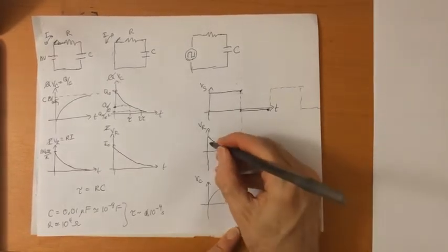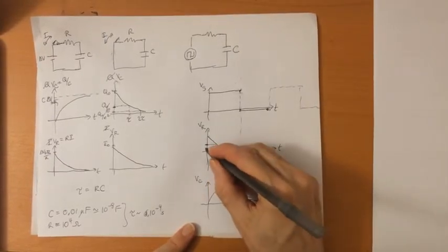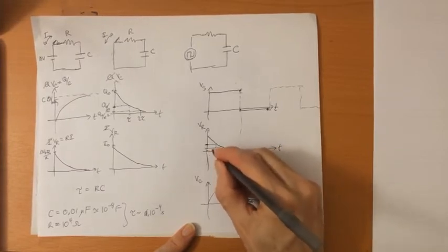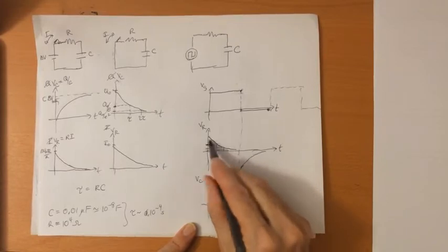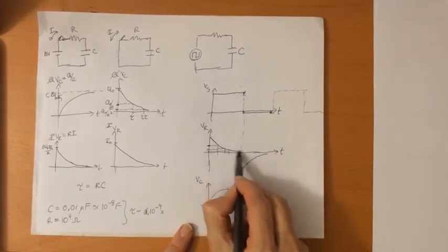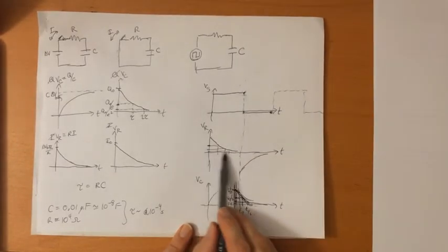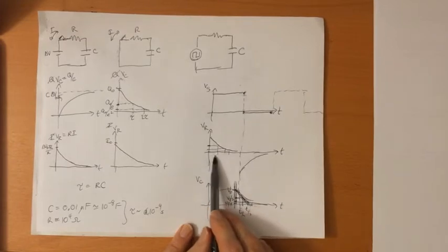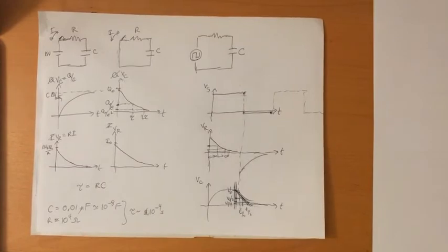And there's also a similar half-life property for the resistor, for both the charging and for the discharging, right? Again, it should be the same amount. I didn't draw this very well, so it might not look like the same. But if you do a careful job of drawing the actual curves that you see on the oscilloscope screen, you should be able to get a pretty good match here. These should be the same time interval. This is usually taken to be evidence that you are looking at an exponential curve and not some other function.